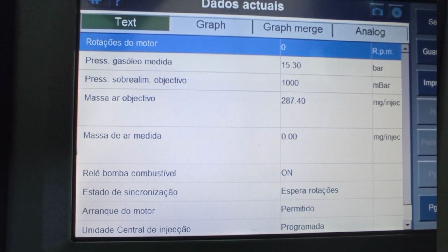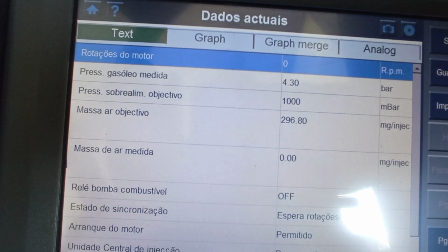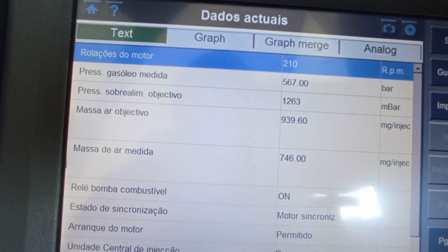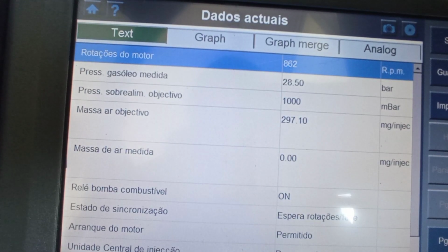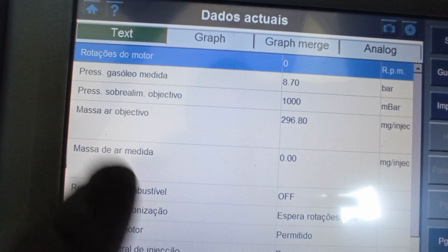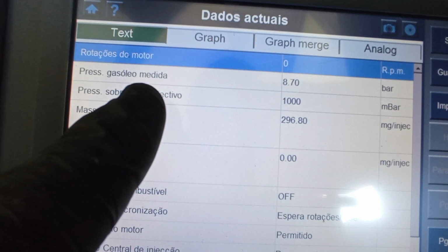So next problem. Now, I guess I saved the best for last. Let's do the cranking here. It will not start. We'll crank. My battery is starting to get low. Okay, what do you see? Everything is okay. So what the hell is going on? So again, watch the RPM and the synchro. Synchronization, RPM, and fuel pressure.